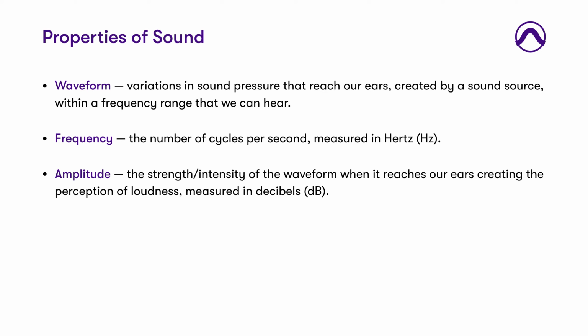As future audio engineers, it's important to remember though that decibels is not a normal mathematical quantifier, which means we can't add and subtract dBs like we do normal math. As you learned last semester, a dB is a logarithmic scale, so just doubling the number does not necessarily make it double. When it comes to amplitude or volume, you need to always remember two values, 6 dB and 20 dB. 6 dB is how much you need to add to your signal if you want to double its amplitude, and 20 dB is how much you need to add to your signal if you want to multiply its amplitude 10 times.